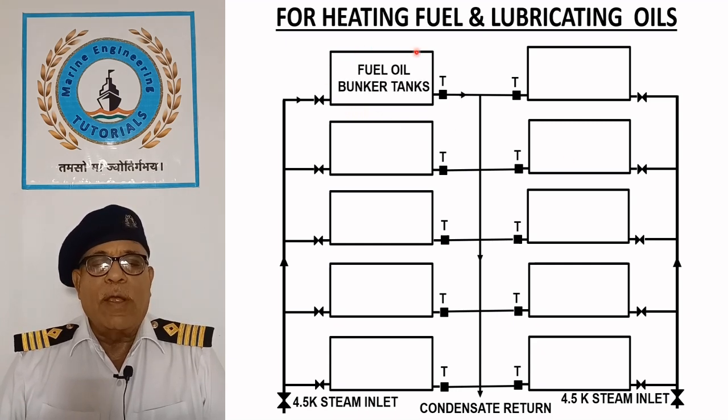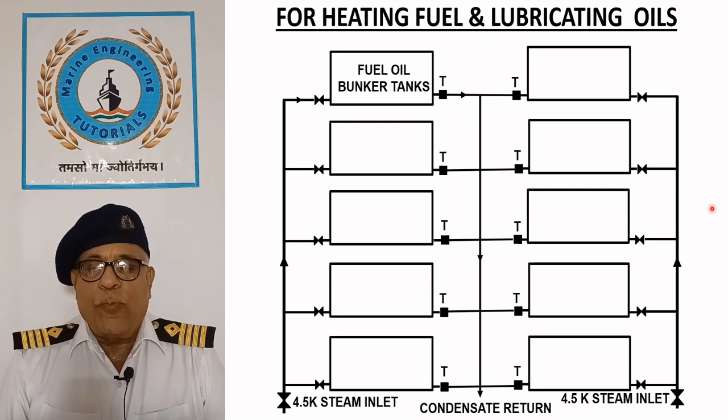Fuel oil bunker tanks. Heavy fuel oil stored in bunker tanks is heated above its pour point, typically to around 45 degrees Celsius, to maintain pumpability and facilitate easy transfer.